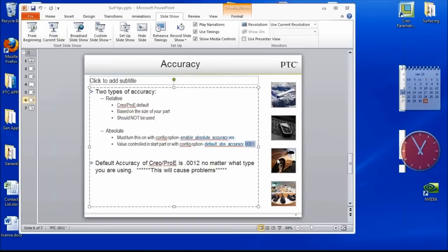Okay, very good. And Tracy, the answer is yes, because there really is no separation between what is a surface model and what isn't. It's just the accuracy of your model altogether. Once you set that accuracy up, whether you're doing solids or surfaces, it's just the accuracy of the model in general. There really is no separation between the way the software looks at it one way or the other.